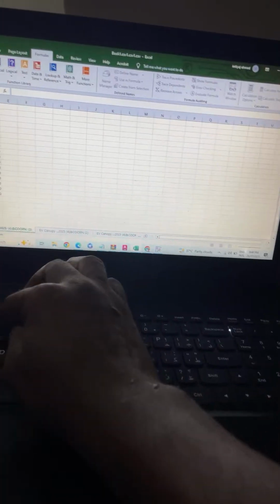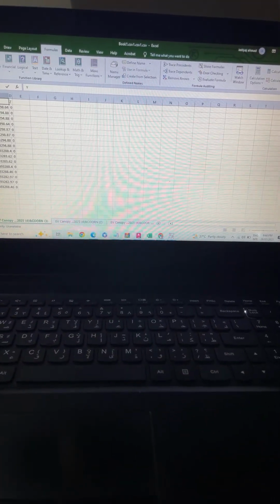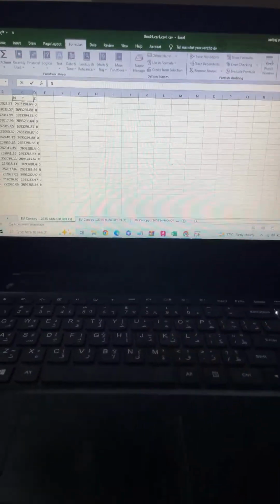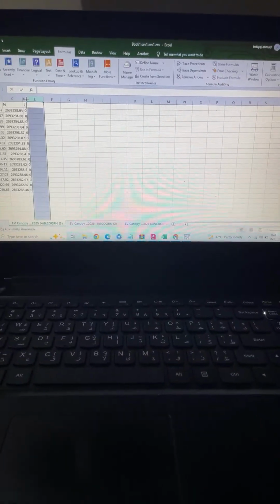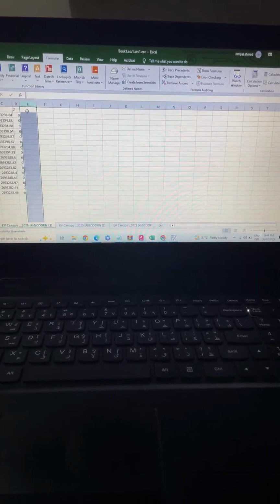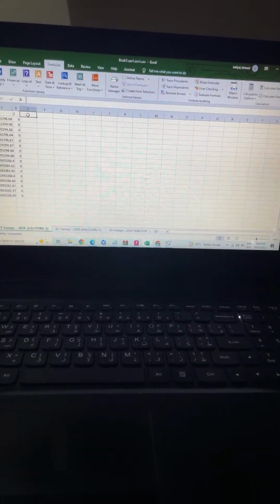We can use caps lock to type the words in capitals. Now, northing and easting, what we call, for that we are telling east and north this time. And Z, you know the value, you know the meaning of Z. Z is the zenith, meaning elevation. And then comes the code of this point. You have to write their code.